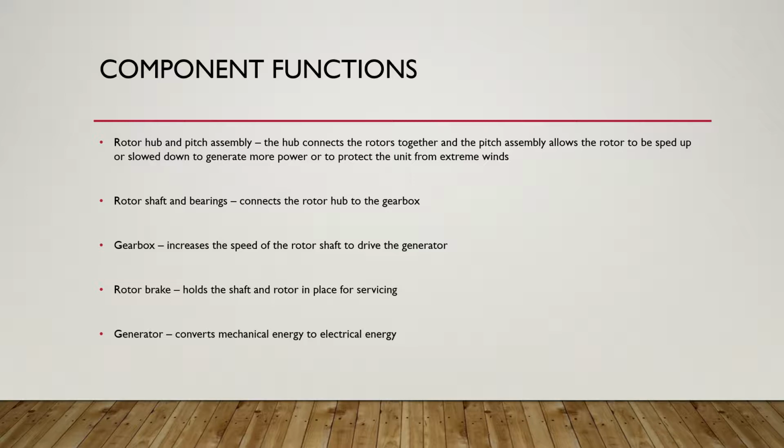The rotor shaft and bearings connect the rotor hub to the gearbox. The gearbox increases the speed of the rotor shaft to drive the generator. The rotor brake holds the shaft and rotor in place for servicing. And finally, the generator converts mechanical energy to electrical energy.